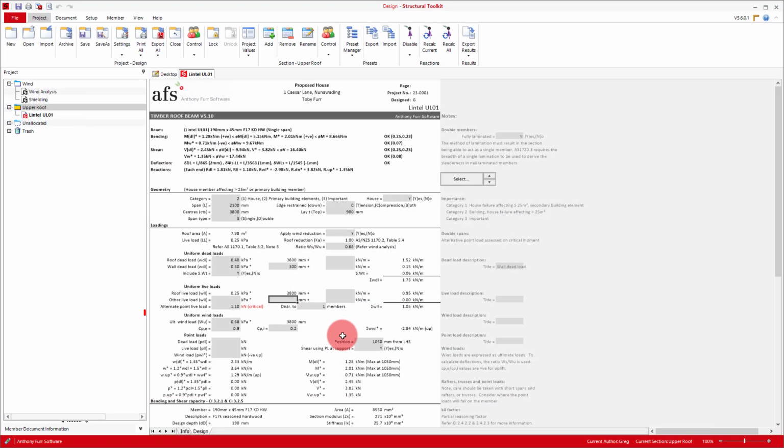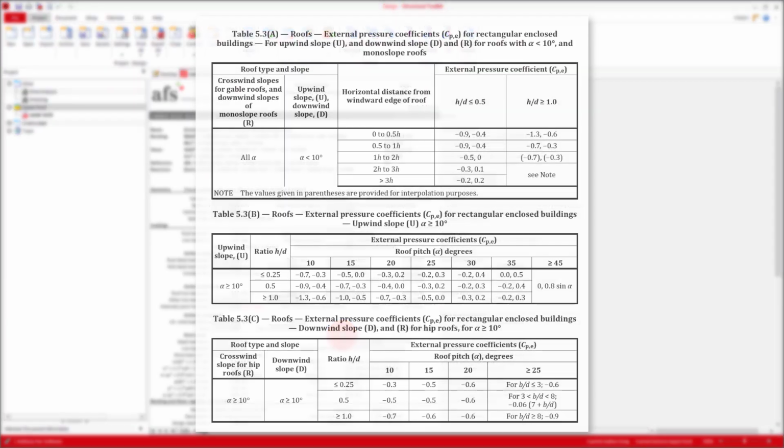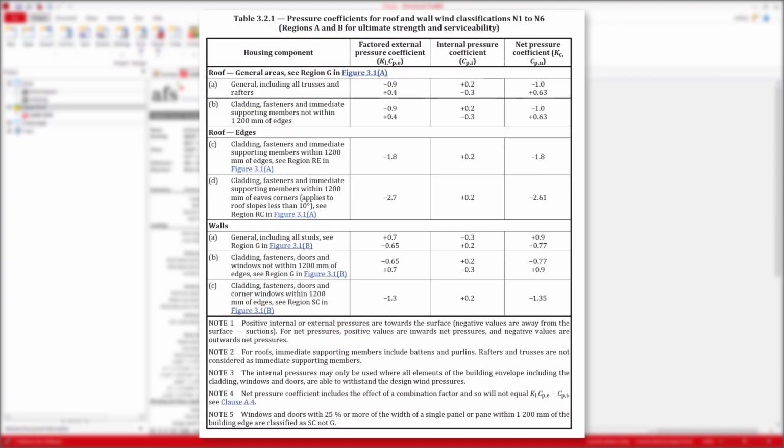Finally, we have the wind load, which includes our new default of 0.68 kPa. We can see here how useful the project values can be, and it will make sure we never miss these values, especially in a case where your wind load may be greater than the standard default. As for our wind shape factors, CPE and CPI, we'll be taking some commonly adopted values for residential design of 0.9 external and 0.2 internal, with positive being upwards. These values come from the wind code, and you'll find they are typically the critical values for a house of standard geometry. You can also look at AS 4055 for more examples of these values, but do note that we are not using 4055 for our design here.